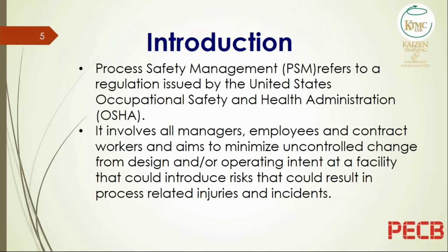There are various approaches to process hazard analysis. As we will see in a little while, the HAZOP methodology is what I use in this particular case. Process safety management refers to a regulation issued by the United States Occupational Health and Safety Administration, OSHA. It involves managers, employees, and contract workers, and it aims to minimize uncontrolled change from design and or operating intent at a facility that could introduce risks that could result in process-related injuries and incidents.